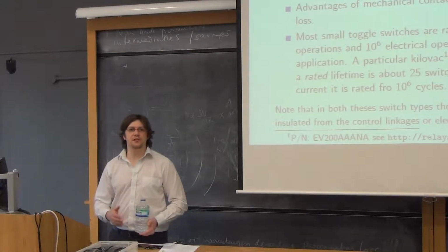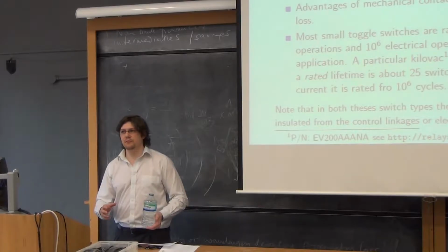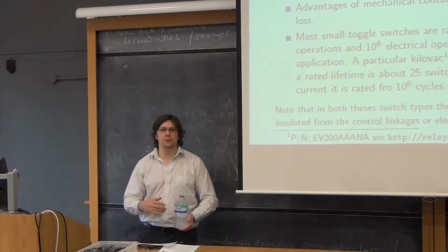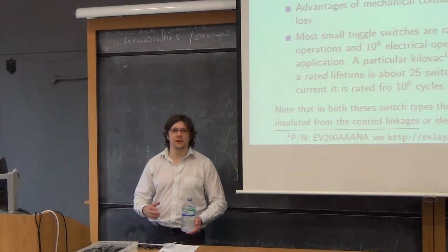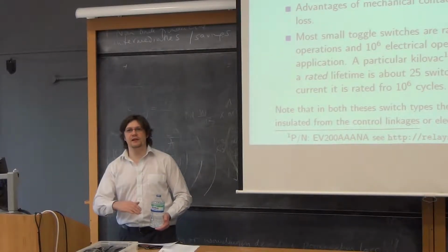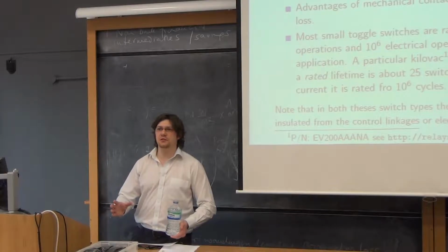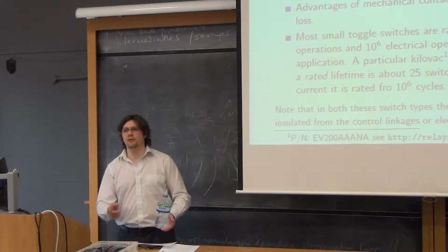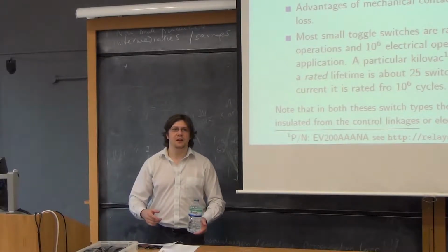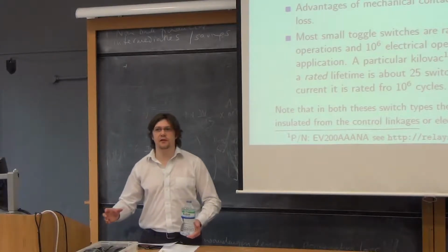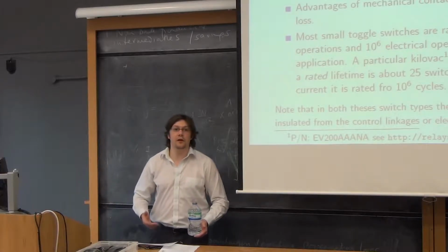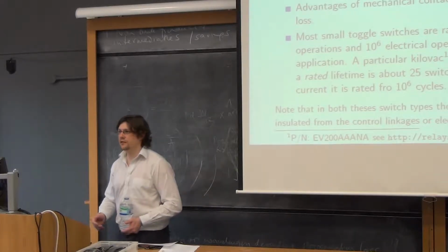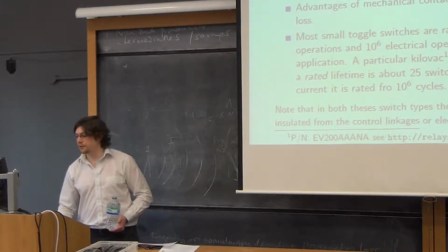So oftentimes in this sort of situation, we have some power semiconductors to decide when the current's on and off, and the relay will be our last line of defence. So we close the relay, power semiconductors do the switching, and the relay passes current without any arcing or any funny business. Then power semiconductors switch off the current, and we open the relay under no current conditions, and then it ends up with a very long life. So you can use the two together to optimise the properties of both.